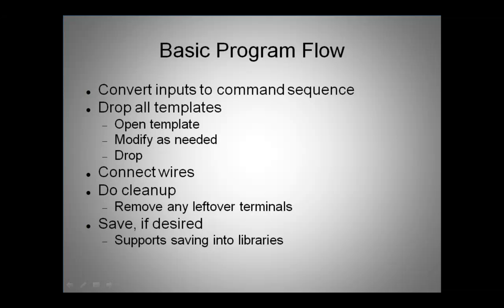It then drops all the templates, and when it drops a template, it opens it, it modifies it as you tell it to, and then it drops it in where you told it to. It then, after all the templates are dropped, connects the wires that you told it to. The nice thing about that is you can specify connecting a wire to something that hasn't been dropped yet. So when you drop a template and you say, I want to connect to this template, and it hasn't been done yet, it doesn't matter. By the time it gets there, it'll be there.